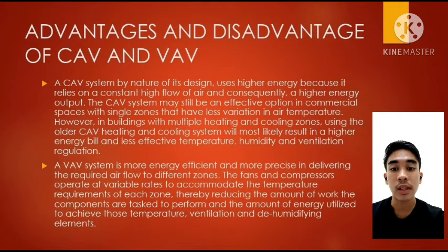However, in buildings with multiple heating and cooling zones, using the old CAV heating and cooling system will most likely result in higher energy bills and less effective temperature, humidity, and ventilation regulation. This is for the CAV, and we move to the VAV system.